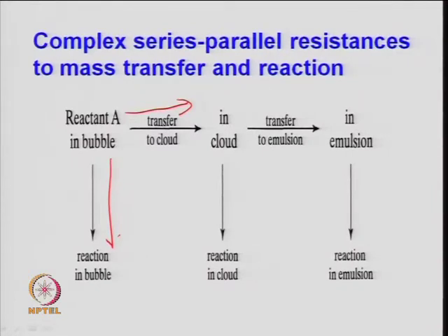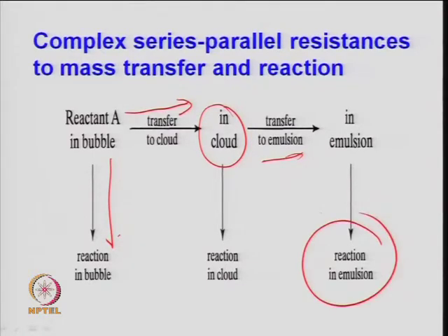So, partly it is reacted and partly it is transferred. So, this is equal to this plus this basically, right, and when it reaches the cloud phase, then again there is a reaction in the cloud depending upon the concentration of the catalyst present. So, there is a reaction in the cloud and the rest is transferred into the emulsion phase, and again when it reaches the emulsion phase, because there is no zone for further mass transfer, it is reacting in the emulsion and finally, it will leave the bed.